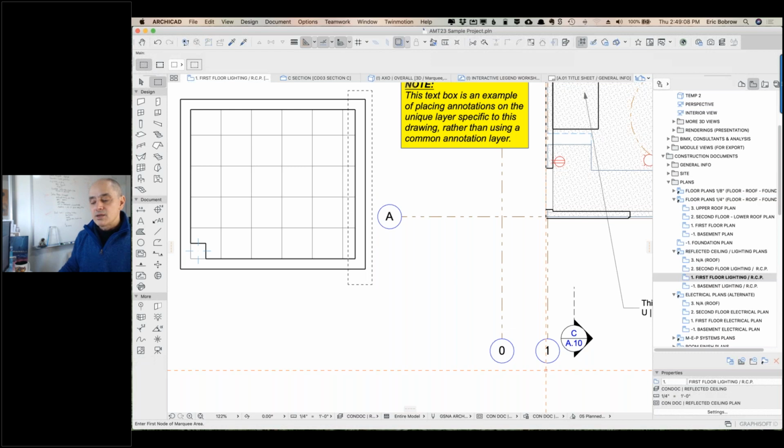But I can go and click on a point like this and bring this in. Now I'm just going to do it approximately to that line. And you can see that I clicked on one point, clicked on another, and everything within the marquee moved or stretched. In this case, the horizontal walls just got shorter here.